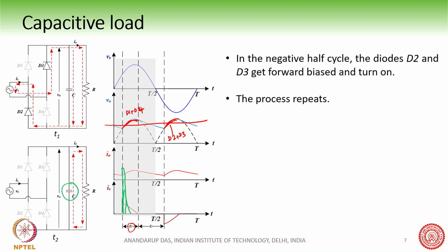In order to maintain a stable capacitor voltage, if it is discharging for a long duration, it must charge, and it is charging in a very short duration of time, so it must take the energy within that short period of time. That is why the input current is becoming very peaky in nature, because it is trying to extract the energy which is required.